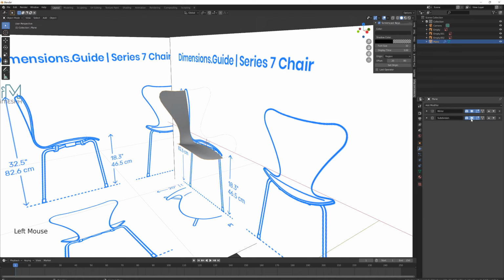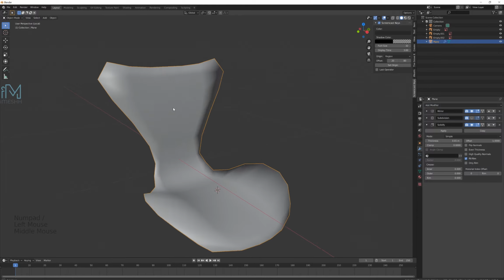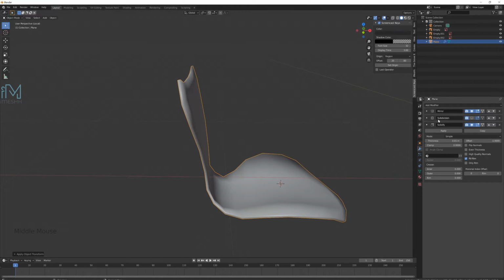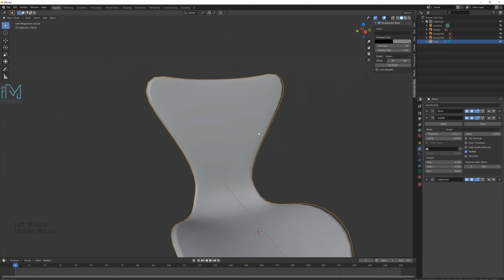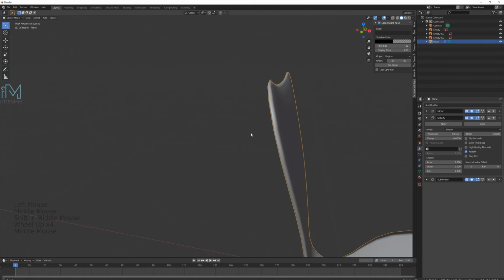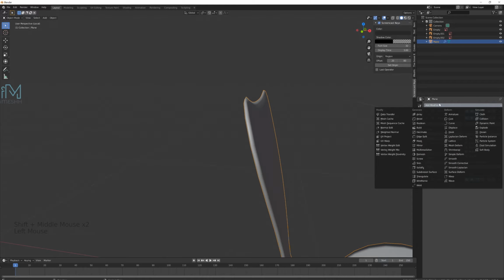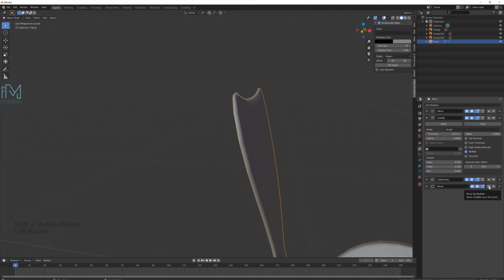I'm going to turn off this subdivision surface, and I'm going to add a solidify. Solidify, and I'm going to press Shift A and click Apply Scale. And I'm going to move this subdivision below the solidify, and now I'm going to press this just to see it. Okay, but we actually want to make this not so sharp. So before this subdivision, I'm actually going to add a bevel as well. So let's move the bevel above the subdivision.